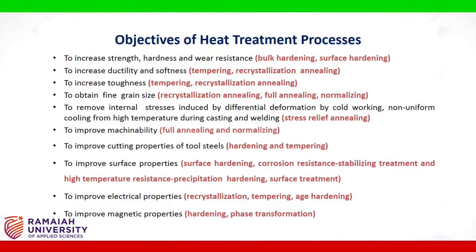To remove internal stresses induced by differential deformation by cold working, non-uniform cooling from high temperature during casting and welding: stress relief annealing. To improve machinability: full annealing and normalizing. To improve cutting properties of tool steels: hardening and tempering.